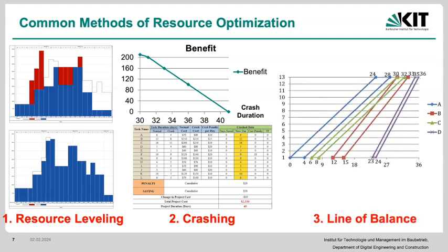And the last one that we're going to be talking about is a line of balance. And this is also dependent upon how you're going to be representing this. Here, for instance, I start from 1, which is here is going to be the units, and these are the durations. And this is basically the flow rate, or sometimes it's called production rate as well, but depending upon how it is, if you start from 0 and basically go there, that would be the flow line method. So that's going to be the representation of it.